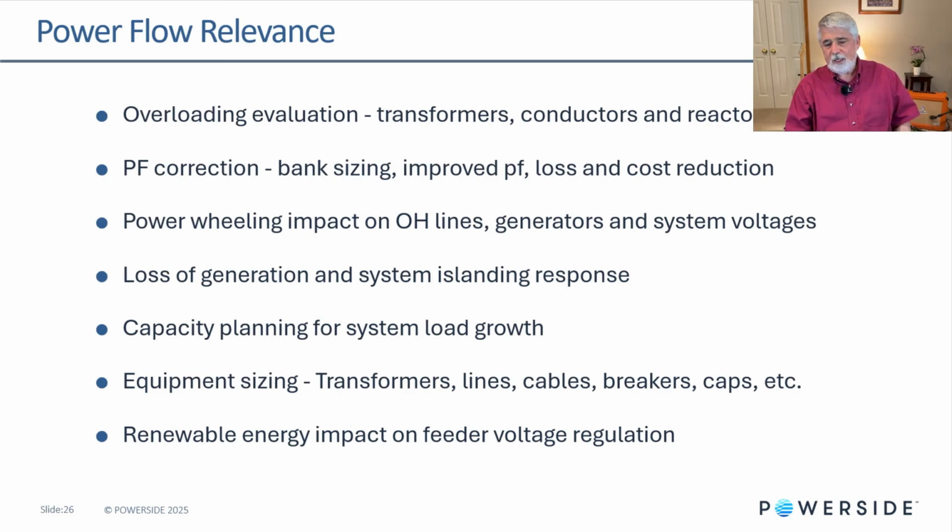Loss of generation and system islanding response. The West Coast broke up into 5 pieces about 25 years ago, if you remember that event. Some transmission line in the Northwest tripped off. If you want to evaluate how each of those islands handled their voltage response across the grid with the particular generation and load condition they were left with, you can run a power flow simulation to determine that. Capacity planning for system load growth.